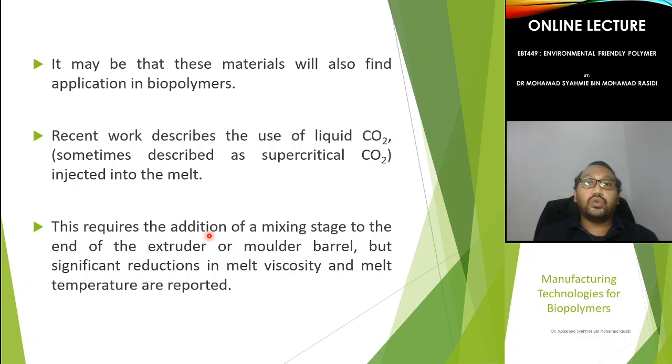Recent work described the use of liquid CO2, sometimes described as supercritical CO2, injected into the melt. This requires the addition of a mixing stage to the end of the extruder or molder barrel, but significant reduction in melt viscosity and melt temperature are reported. So supercritical CO2 or liquid CO2 will help to reduce the melt viscosity and melt temperature when processing biomaterials or biopolymer inside an extruder.